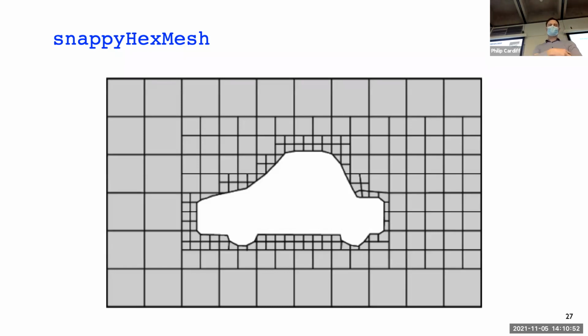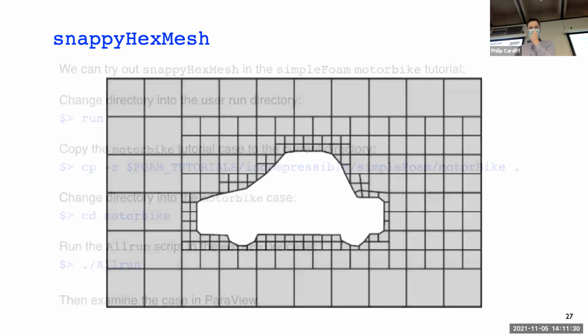And then one other step, I haven't shown it here, is the final part, where you can add layers. So just like in ANSYS, though I don't think we turned it on in ANSYS, the disadvantage of the Cartesian-based meshing approaches is that the worst cells are right on the surface of the car. So if you're interested in the drag on the car, your greatest mesh errors will occur where all these cells are weird shapes on the surface. So to counteract that, you can grow layers. What snappy hex mesh does is it pushes back that mesh and then tries to add nice layers of perfectly orthogonal cells. So that's a final step. Typically that is used. I can't remember for the OpenFOAM tutorial whether I had that turned on or not.